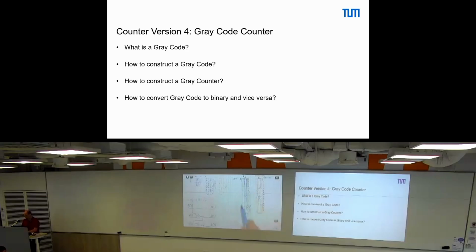And in the other cases, it's inverted. And if the XOR of the 3 bits is 0 or not, that is effectively the output for B1. So we can take B1, feed it back into the XOR, and generate with G0 the B0. So that's what I have here. That's one direction.